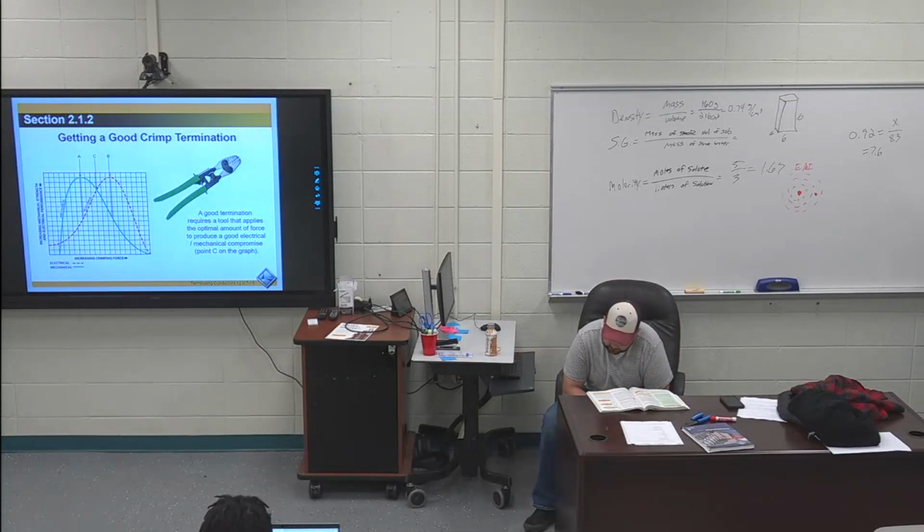Crimping tools, 212. The last sentence on page 23 is an online test question. Using a crimping die that is too large or under crimping gives poor electrical performance. A die that is too small or over crimping gives a very weak mechanical connection because it literally destroys the crimp barrel and weakens the conductors that it's joining.